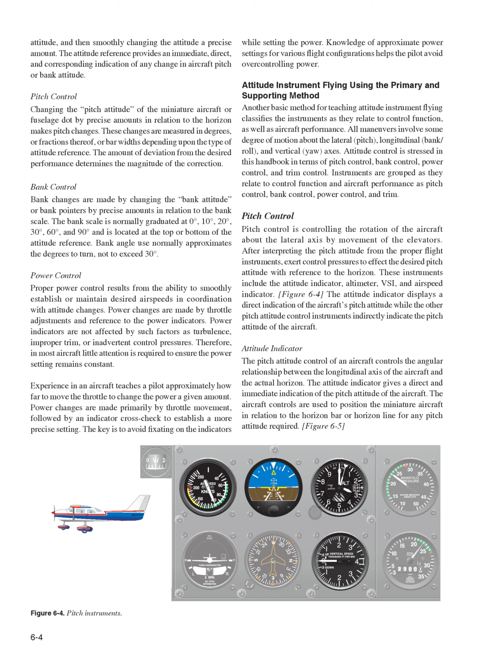Attitude instrument flying using the primary and supporting method. Another basic method for teaching attitude instrument flying classifies the instruments as they relate to control function, as well as aircraft performance. All maneuvers involve some degree of motion about the lateral (pitch), longitudinal (bank/roll), and vertical (yaw) axes. Attitude control is stressed in this handbook in terms of pitch control, bank control, power control, and trim control.